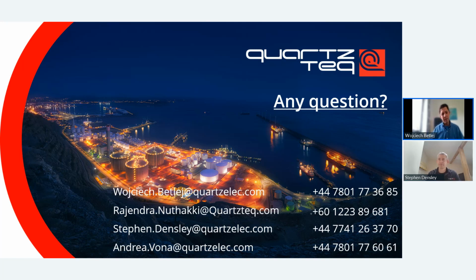Right. So the answer is not as simple as you might think. So there's 2 ways to look at partial discharge, but to be honest, there's only one good way to do it. And you need to remember that every machine is unique. Every machine, even if it's a sister machine manufactured at the same time, in the same factory, will have a different PD value. So the ideal situation is to monitor the PD value from the beginning when the machine is online. So that's why it's so difficult to determine the right or wrong PD level.